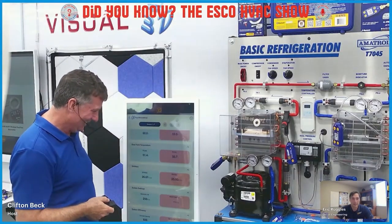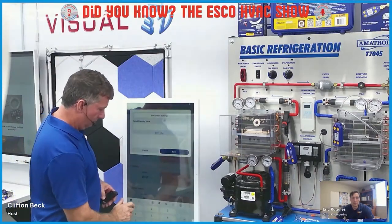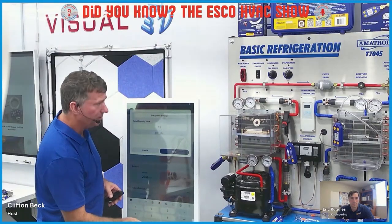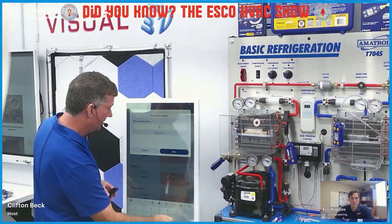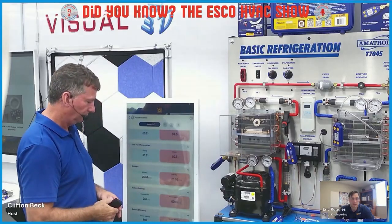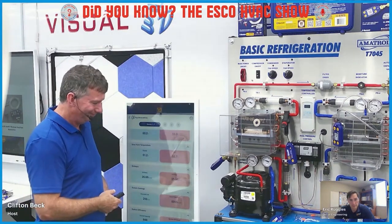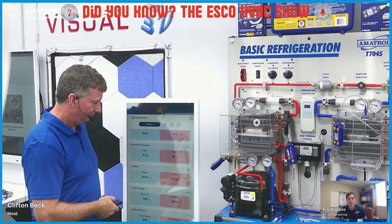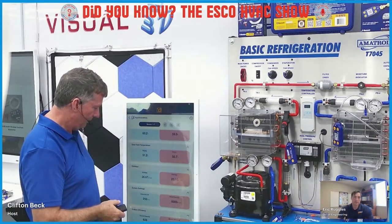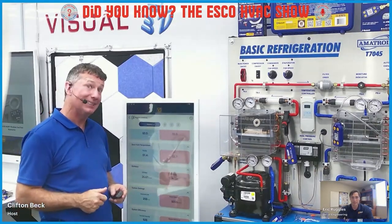That's fair. And then you add this capacity as well, the red box on the right, a rated capacity of the system. I'm just guessing on this one. I don't know what the BTU of that one actually is, but let's just say it's 6,000-ish. Okay. Right. And then it'll use the difference in enthalpy and the airflow to calculate the actual capacity of the system, and then give you a system efficiency number based on what it's actually running compared to the rated capacity. Oh, okay. All right. Getting closer. Getting excited now. Okay. What's next?